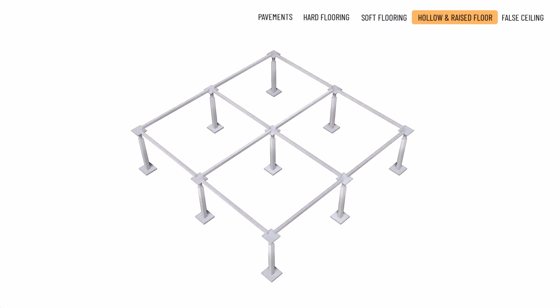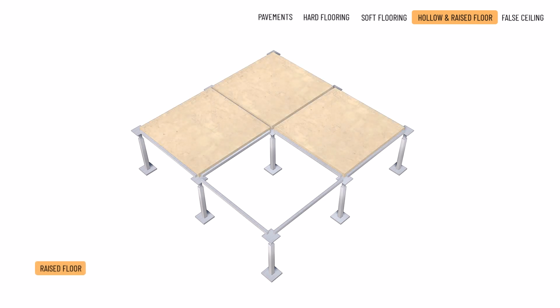Unlike hollow floors, which are non-demountable, raised floors are constructions that can be dismantled without damage, so elements can be removed individually at any time. The 60 by 60 centimetre floor panels rest on height-adjustable metal pedestals and can be finished with any desired covering, either factory applied or installed on site. For heavier loads or greater heights, metal bracing rods connecting the pedestals provide additional reinforcement.